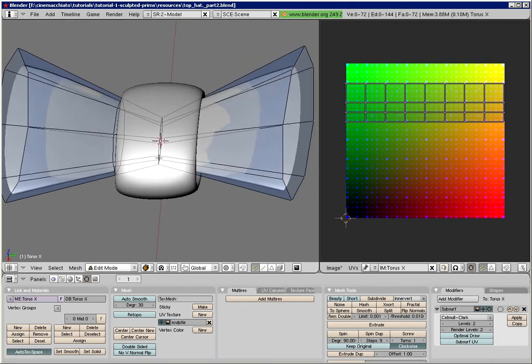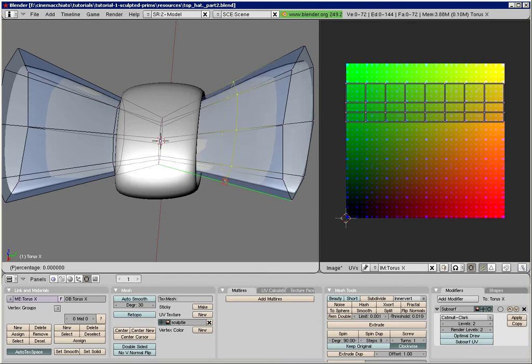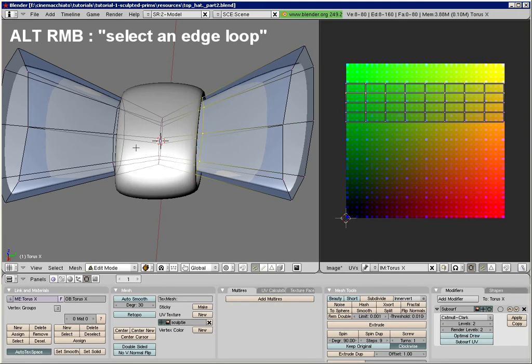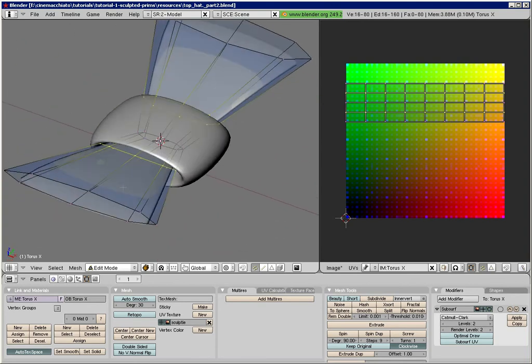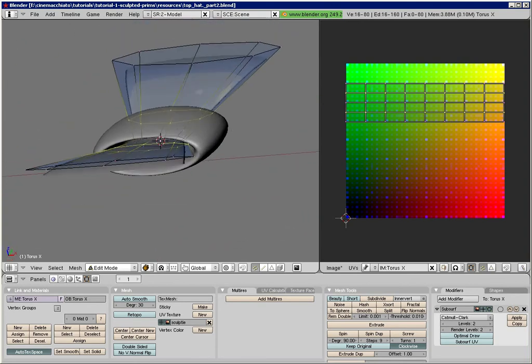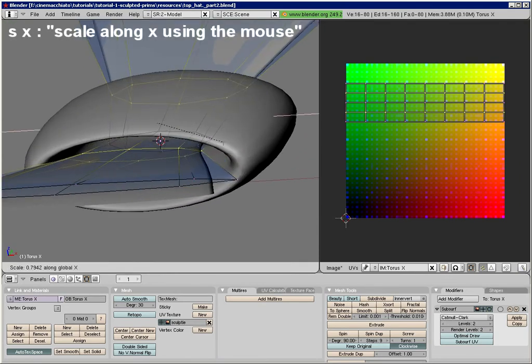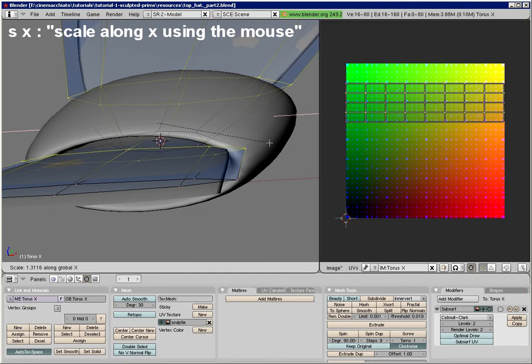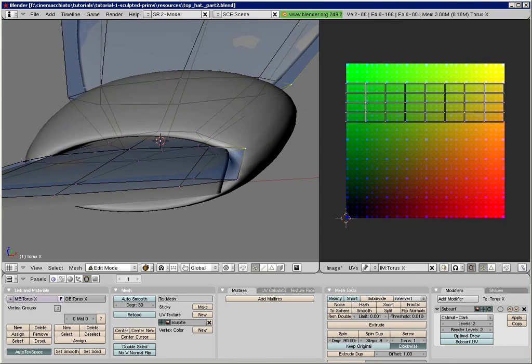Please select again the loop division tool by pressing the Ctrl key, followed by the R key. Now it is much easier to find good loop locations. Click the left mouse button again, and shift the new loop to your desired location. Now select both loops. Hold down Alt, and right-click on the first loop. Then hold down Alt and Shift, and right-click on the second loop. Scale up both selected loops along X until they touch the adjacent sculpting. Then select the outer vertices of the loops.